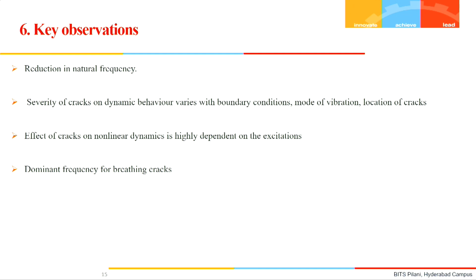The effect of cracks on nonlinear dynamics is highly dependent on the excitation. We have also seen that the same structure, when excited with a single frequency excitation, gave a different type of response. Basically, the dominance of a particular mode was happening in some cases for the intact beam, and that completely changed with the two frequency or multi-frequency excitation. When we excited with a different excitation pattern, the crack affected the different modes differently. That is what we have seen.